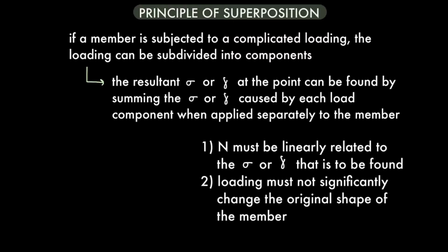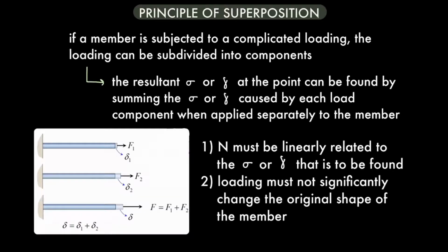But the principle of superposition has 2 conditions that need to be met if we use it. First, the loading N has to be linearly related to the stress or displacement. Second, the loading cannot significantly change the original geometry of the member. If those 2 stipulations are satisfied, then we can use the principle of superposition as it is shown pictorially on the left.